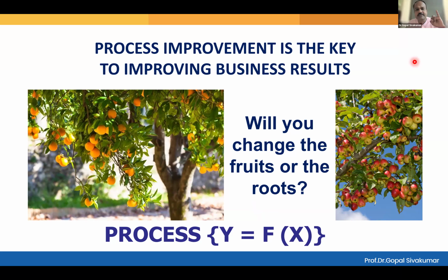Identification of the root cause, and then before relationship, validate the root cause. Identification means just based on experience, people telling, but you must verify it experimentally. If you verify it experimentally, validation happens. Identification of root cause, validation of the root cause, relationship of the root cause, and finally sufficiency of the root cause. These are the four stages in root cause analysis. If you know this, you can fix any kind of problem, no matter however complex it is.